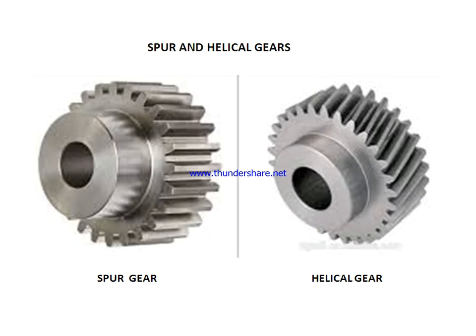Here is a comparison of the helical gear tooth with the spur gear tooth. You can see the teeth here are parallel to the axis of the gear blank, but here the teeth are at a certain angle to the axis of the gear blank. So the inclination of this gear tooth with the axis is the helix angle.